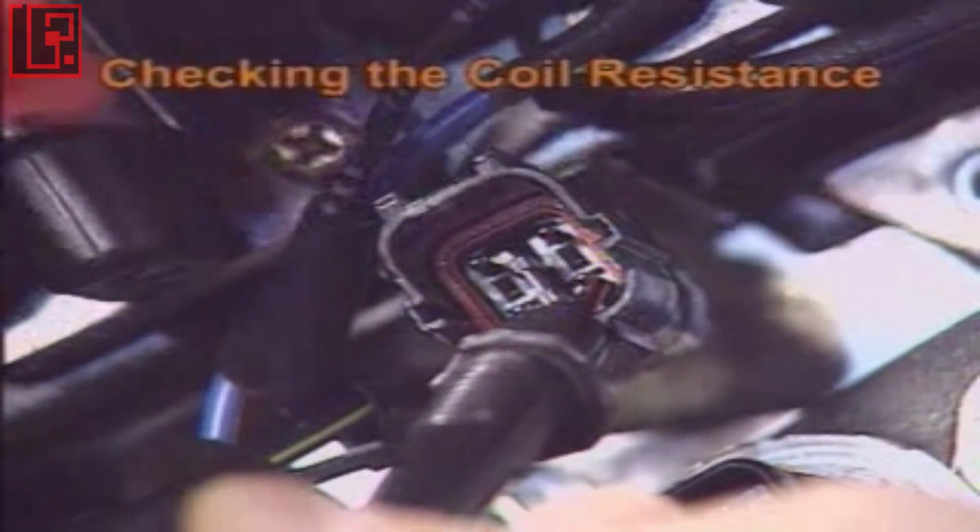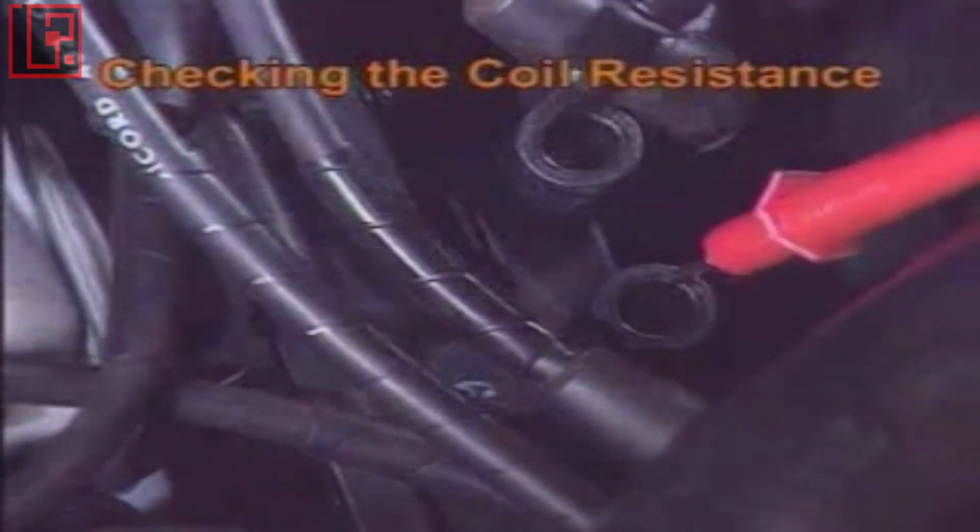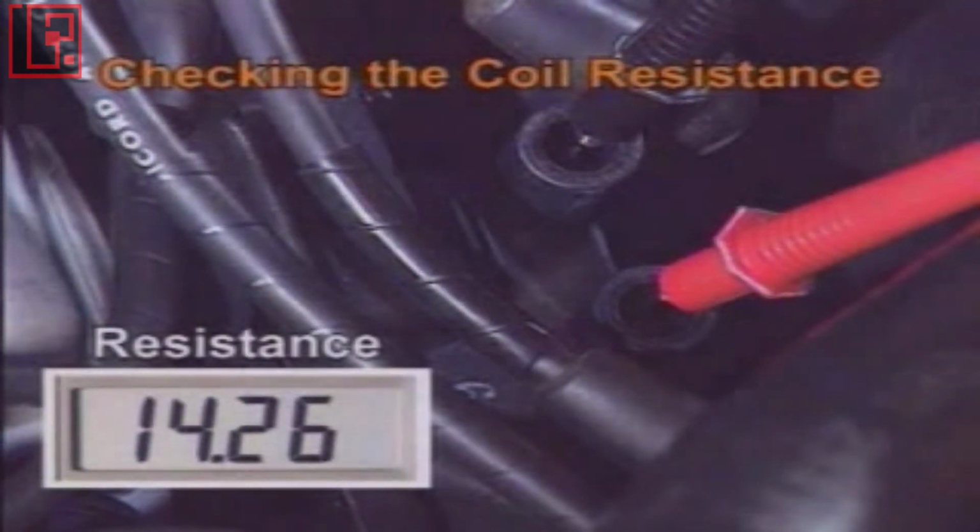To check the coil resistance, remove the coil connector and measure the primary coil resistance at the connector. As for the secondary coil resistance, remove the high-tension cable and measure the resistance of the secondary coil, since each coil resistance value differs depending on the engines. Please refer to the shop manual for the correct values.